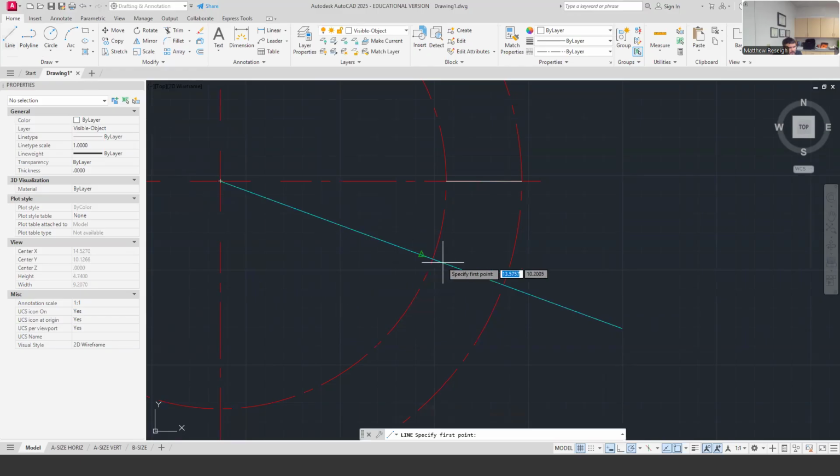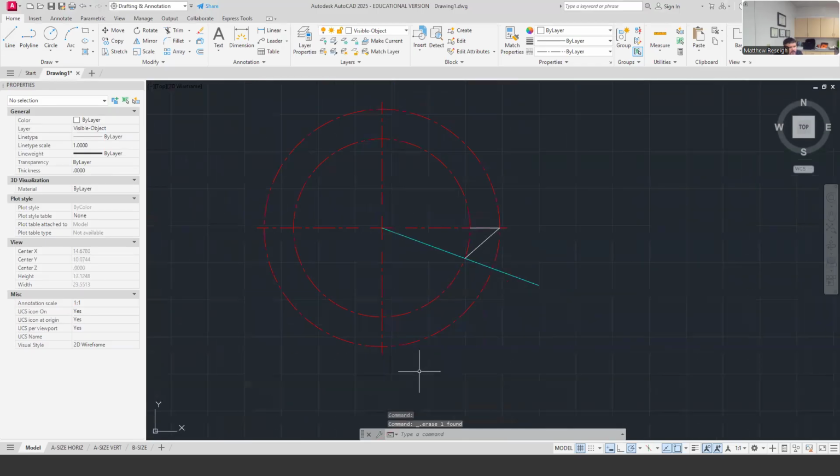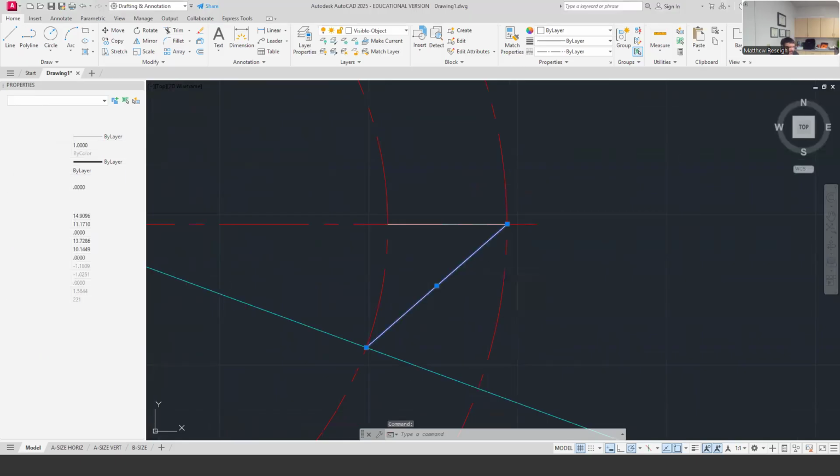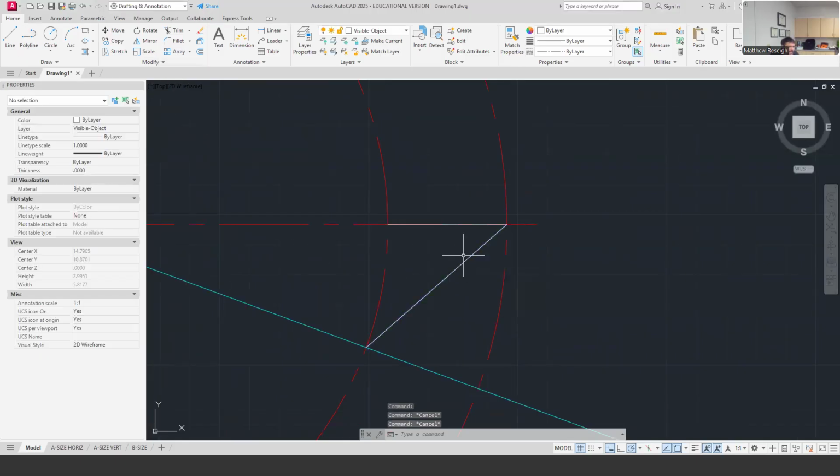But I feel like I'm going to draw here to here now. Those are the two straights. I probably don't need that necessarily, because what I'm looking for is just one tooth, which is from here to here. So technically I probably didn't even need to draw this in. I can delete it, but I already had the intersection point that I needed. So there's one. Now I just need to array that around 18 times. And I could maybe join this before I do that. I think when I do my array, it'll all be joined though.